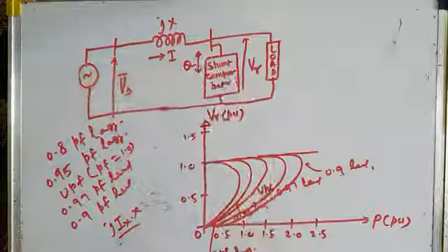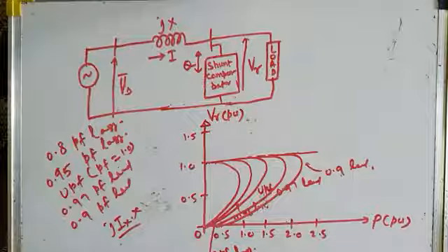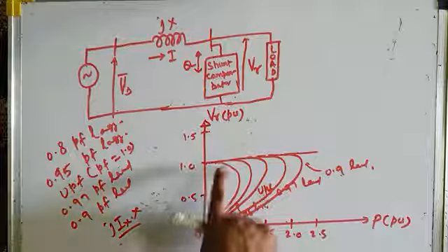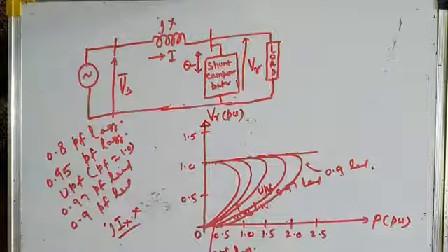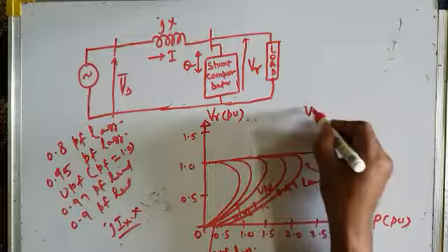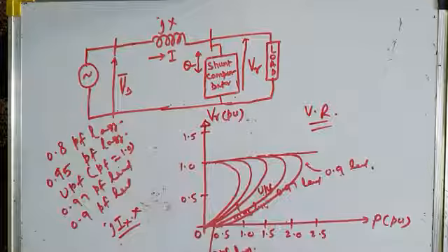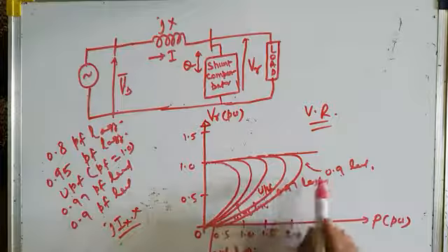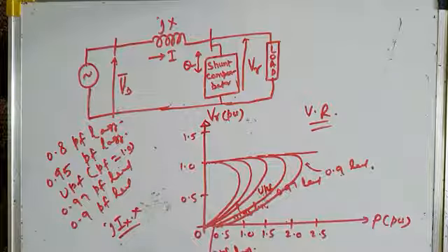The compensator provides the reactive power and hence voltage support, because of which there is less drop in the voltage. The receiving end voltage remains very nearly equal to the sending end voltage, and voltage regulation is improved. And secondly, the nose points, which represent the voltage instability points, are also shifted towards the right. So therefore voltage stability is also improved.